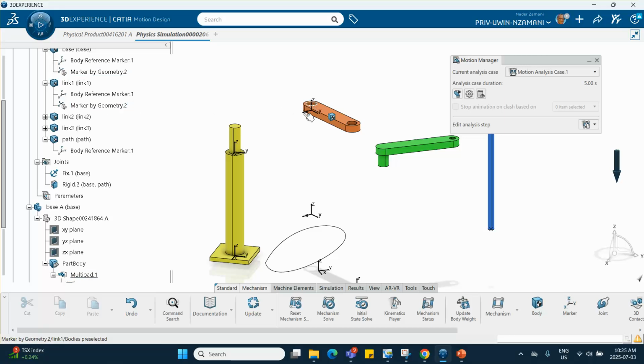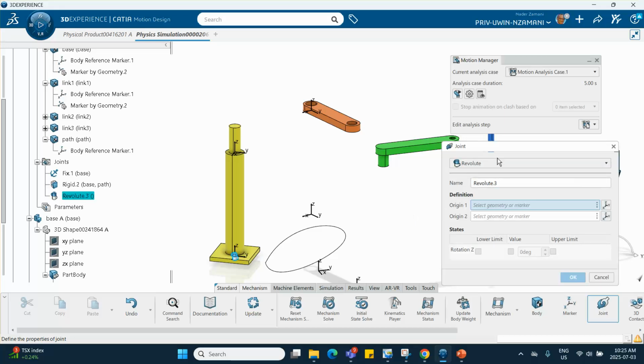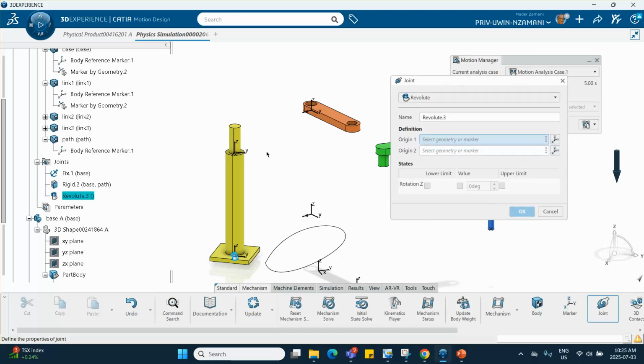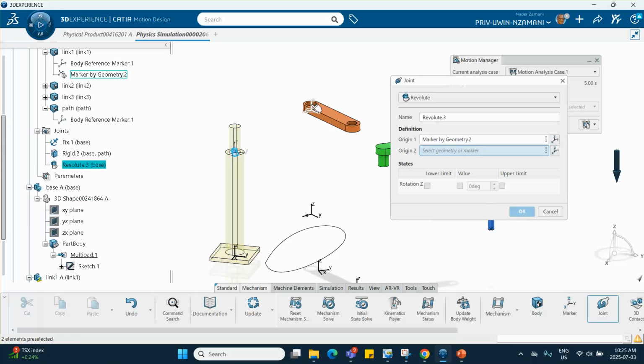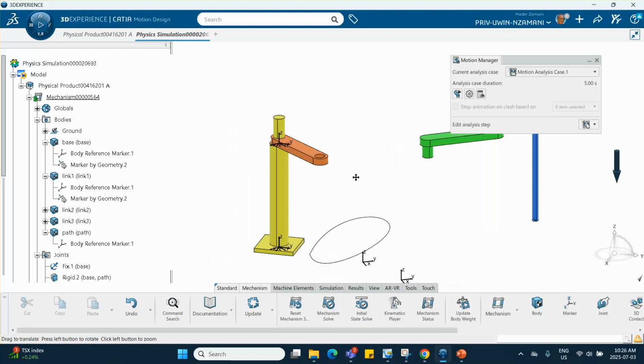And now I'm in a position to create that revolute joint. You can do all the markers for the other ones too and do it at the end, but I'd rather do it right now. So we go to joint, revolute, and I will select the two markers. Now, what are the two markers? The order of it doesn't matter. I select this marker and that marker, and it better end up in the position that we want, right there.